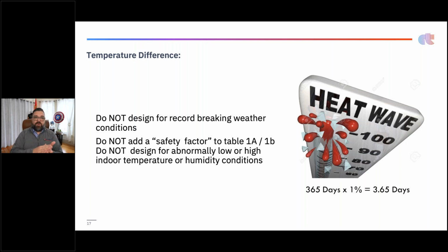say it's 95 or almost 100 degrees out, it obviously can't cool to 75 degrees, but the system is running all the time and it's removing the moisture. It might reach 76, 77 degrees inside, and it might be 45% relative humidity, and we'll feel comfortable. So what that is, it's in the middle of the psychrometric comfort zone.